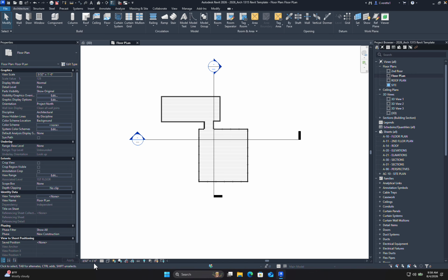However, that's looking like a really big scale. So again, I'm going to change my scale. Notice what happens. What changed, the building or the annotations? It actually reveals that the annotation size is based on my scale, right? Something that I didn't know graphically standard-wise until, honestly, I started learning Revit. So some of us who have gigantic graphic scales out there, maybe we start to realize we don't need those. It's actually taking up the drawing, right?